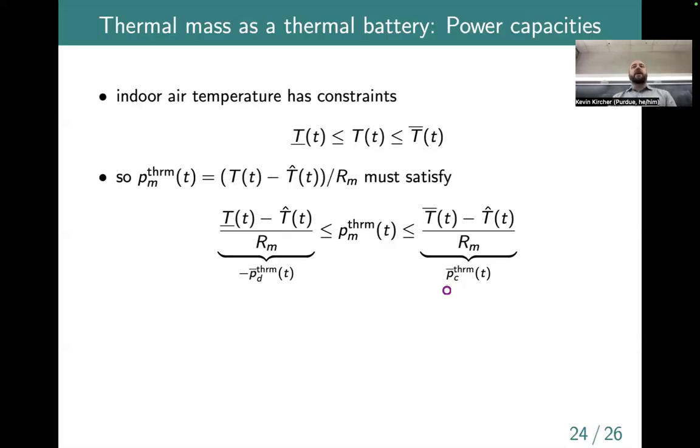Yeah, so if we wanted to model that sort of direct coupling of the thermal mass, suppose we cared about the thermal mass in that wall, which is an exterior wall, then we would probably assign another resistance between that mass and the outdoor air. And that would represent direct heat transfer with the outside. Okay. And you could do that, and you could follow through the same steps that we've done in the slides.